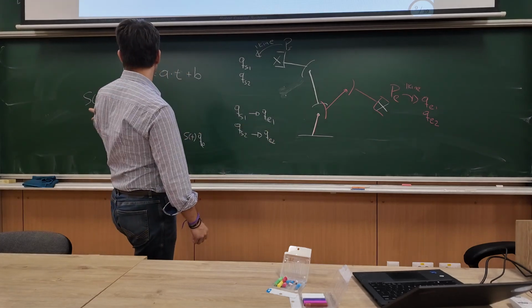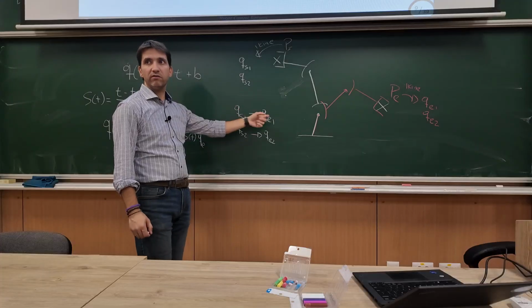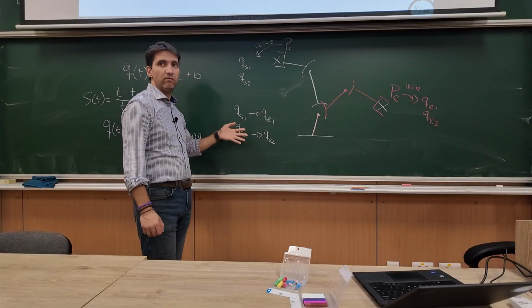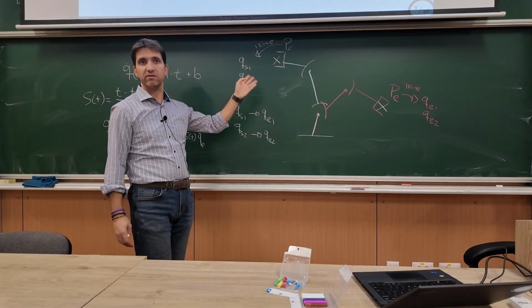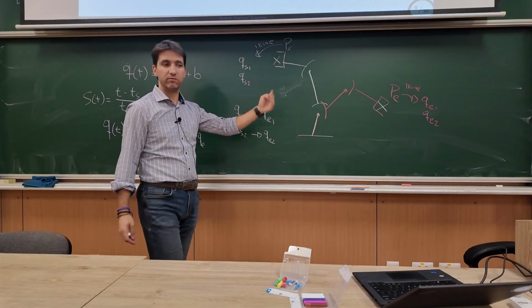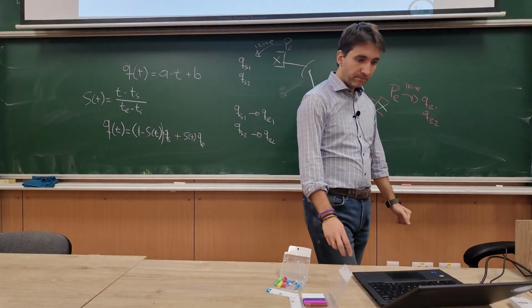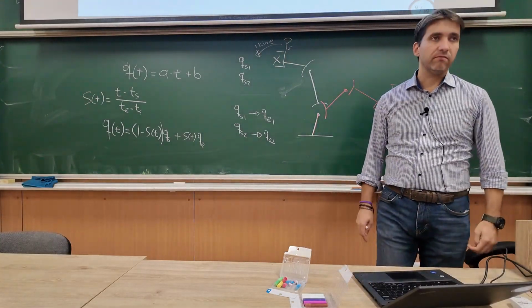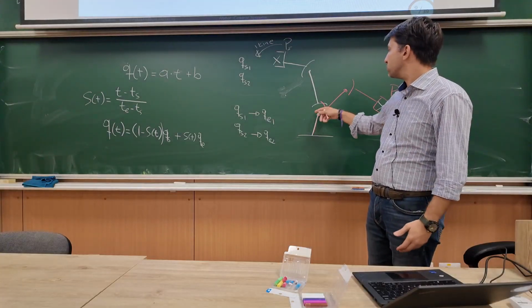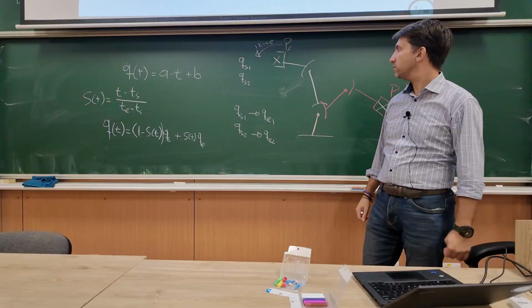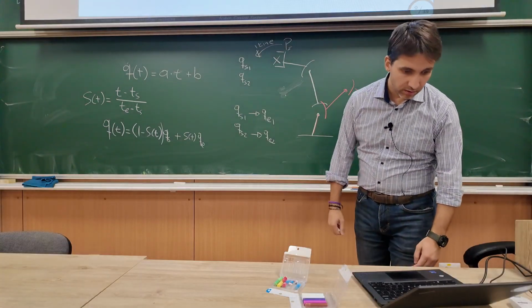So basically what we're doing here, this is my starting value, this is my ending value. I can interpolate separately and then figure out what's the transition that takes me from this pose to that pose. Right? And we can interpolate them separately because they're basically independent. Like we assume, and it's a good assumption, that each joint can move independently. Right? Okay.